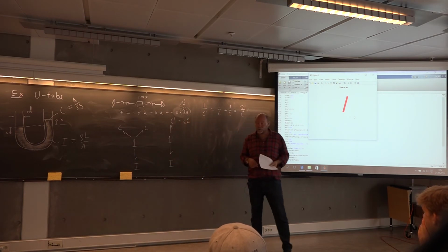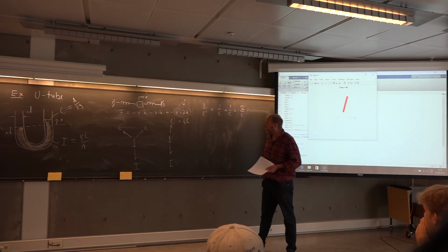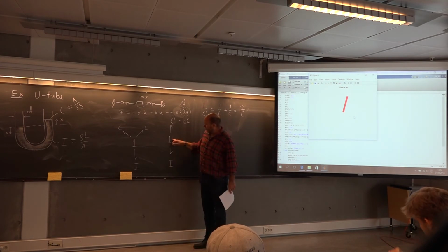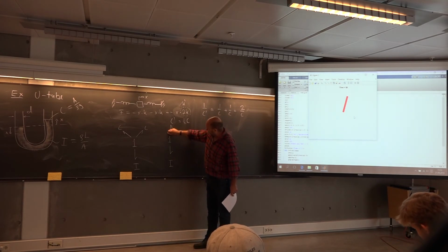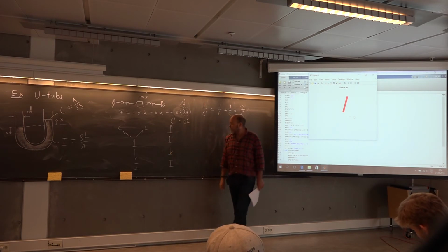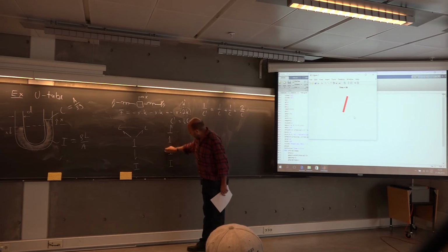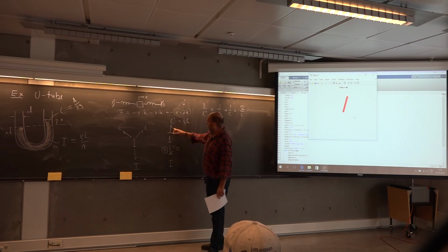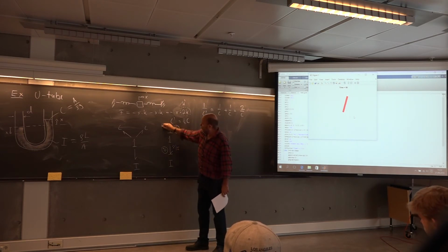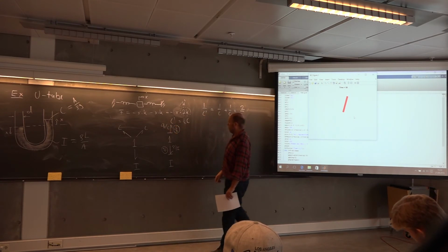What about the equations? How can we find them? Well, we insert the causal strokes for the compliance. Should be here. Inertance should be here. So it's a second order system. And here we had P dot with a circle, P over I. Here we have Q dot circle, and on the other side Q over C.